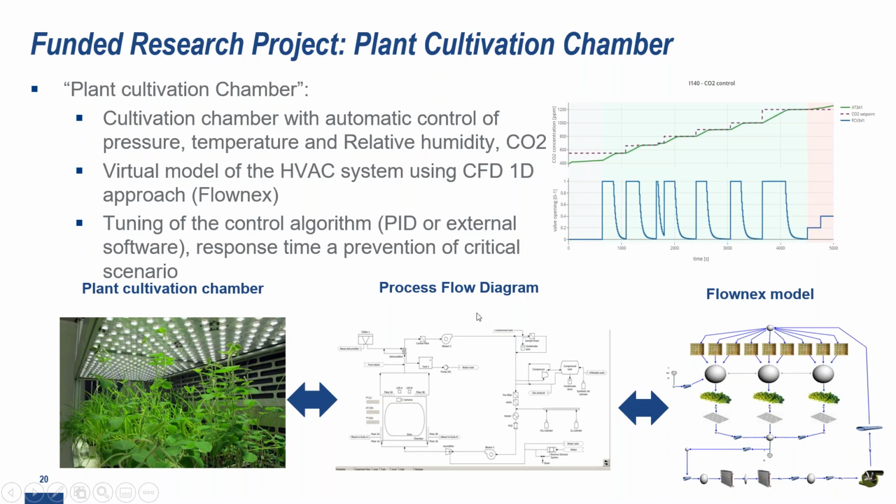So this is how you can apply the design of a virtual model, starting from scratch, and then tune your Flownex model to reach the desired condition, with a detailed calculation of the energy consumption. Moreover, you can be more precise in the selection of the fans or the pumps or the primary and secondary lines to eventually reduce the total consumption of the system.